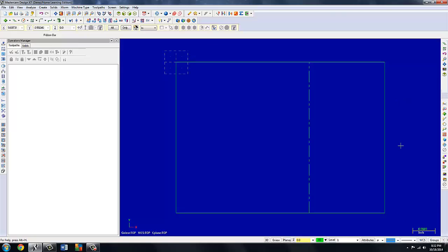Now I can start putting in some of the parallel lines that will help me with my geometry. One of the main things I see is that there's a lot of things dimensioned off the bottom of the part cavity, if you will, and that line is 2.75 off the bottom. So I'm going to put that one in. Create line parallel. Put in my 2.75, enter. Select a line. Indicate the direction. And that line will represent the bottom of my part cavity. Both of these have a lot of dimensions originating from them. So that's a good thing to get going.